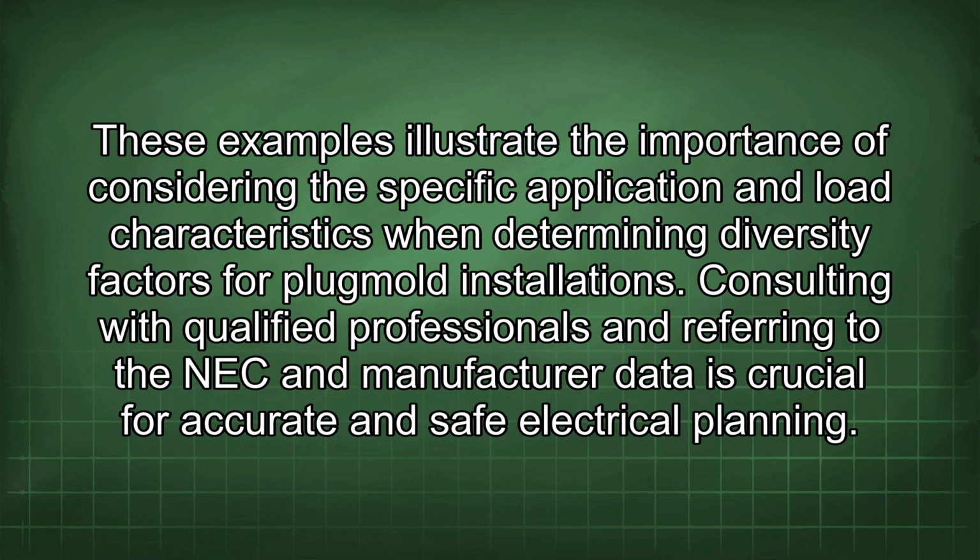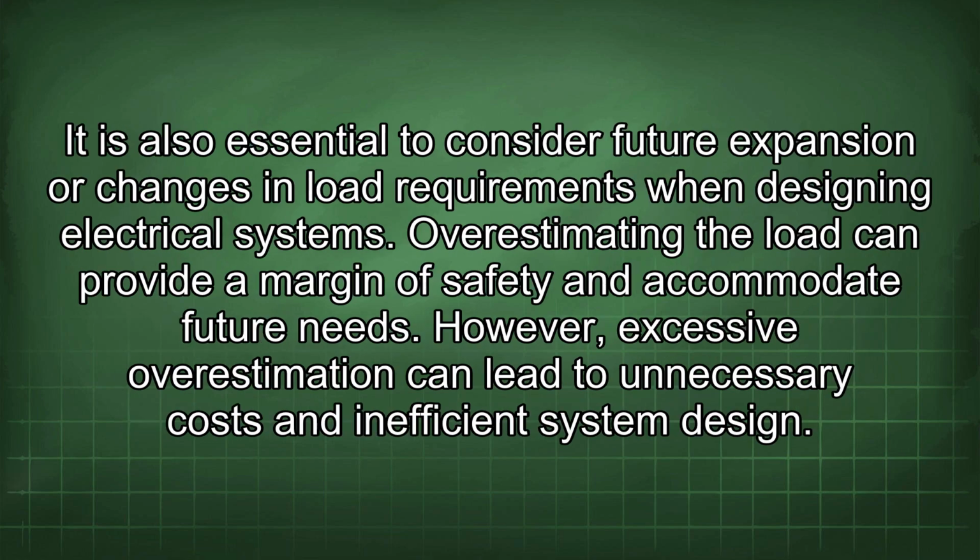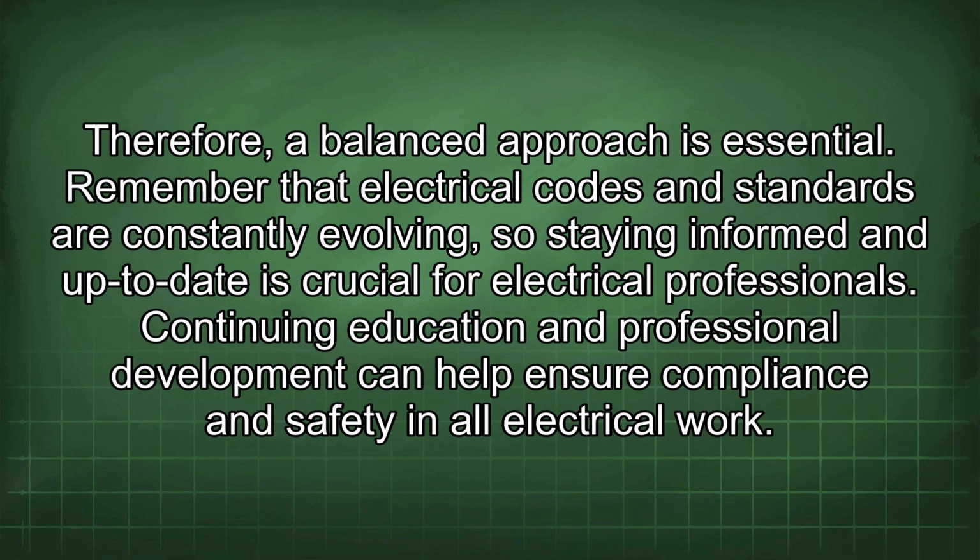Consulting with qualified professionals and referring to the NEC and manufacturer data is crucial for accurate and safe electrical planning. It is also essential to consider future expansion or changes in load requirements when designing electrical systems. Overestimating the load can provide a margin of safety and accommodate future needs. However, excessive overestimation can lead to unnecessary costs and inefficient system design. Therefore, a balanced approach is essential.